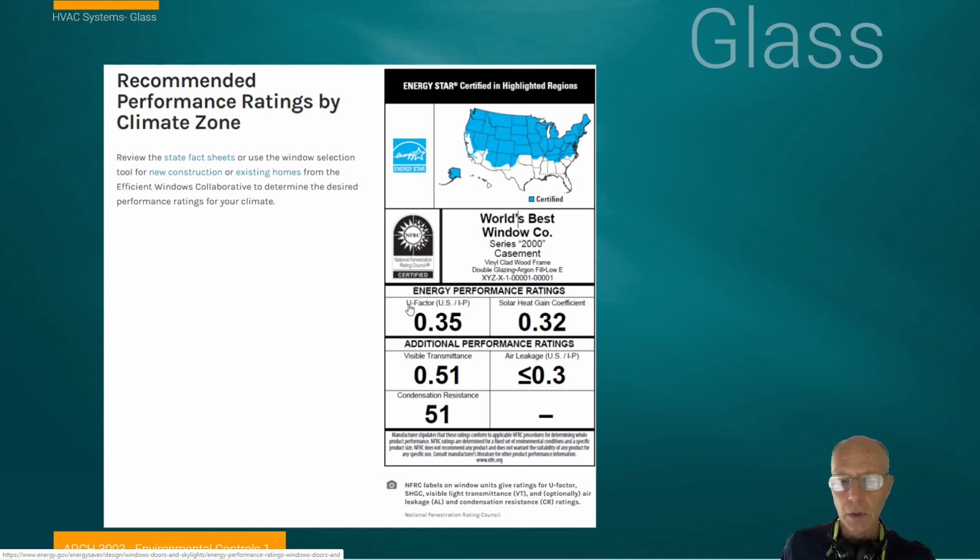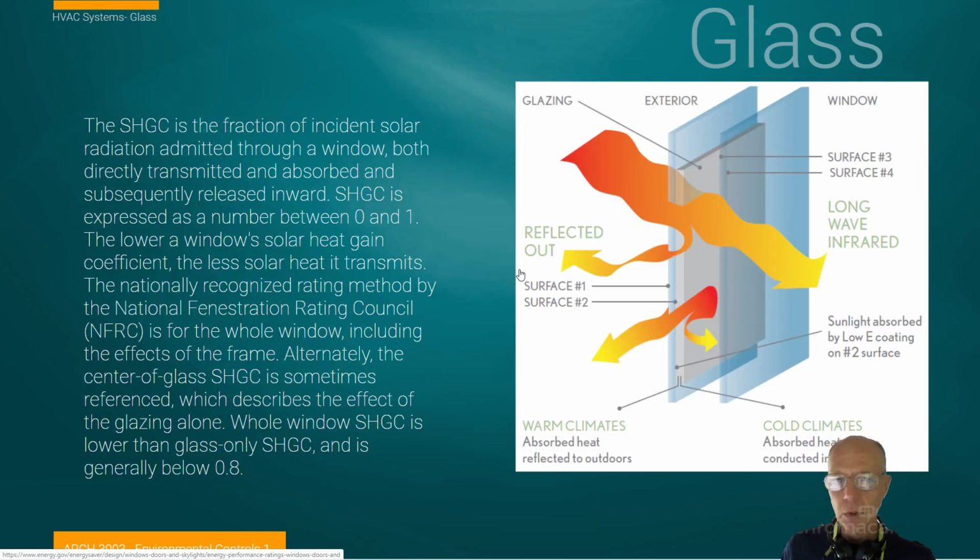And then we get the U factor. Once again, that's a reciprocal of the R value of it, and that's how we measure glazing systems. We have our solar heat gain coefficient because this has a low E coating on it. It's also double glazed, and there's another term that's introduced here, and that's argon. Argon is the gas that fills up that space between the glass.